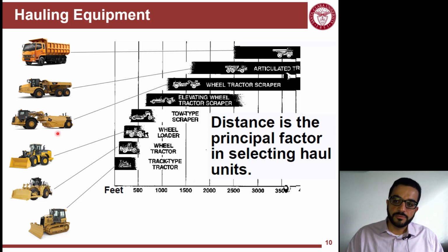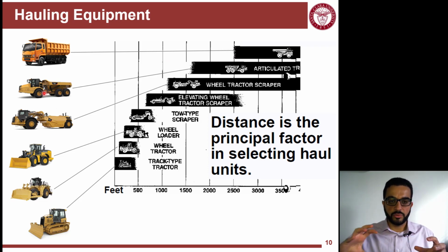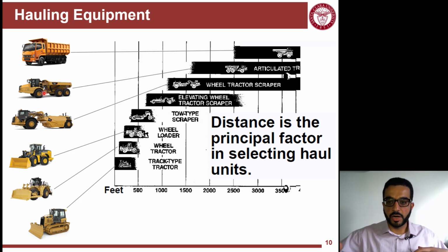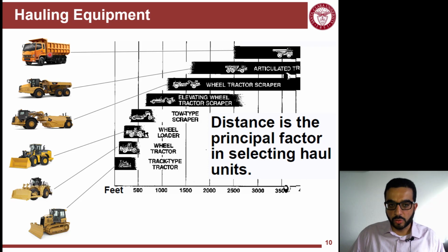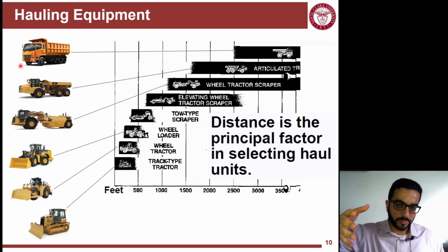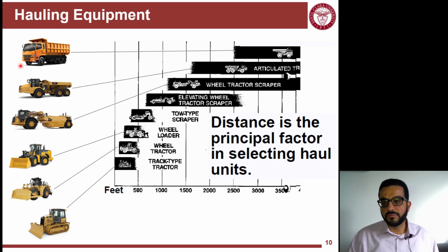Trucks can be different shapes. This is what we call the articulated truck. You'll find at this point there's a big, huge hinge. So the box of the truck at the end can rotate at a different angle than the cabin of the driver. That makes the equipment more versatile and able to drive on rough ground surfaces. Compare that to the regular hauling trucks we see on the roads. These are fixed, rigid frames. If you drive them on rough grounds, they either flip or are not stable. It will not be a safe drive for them.